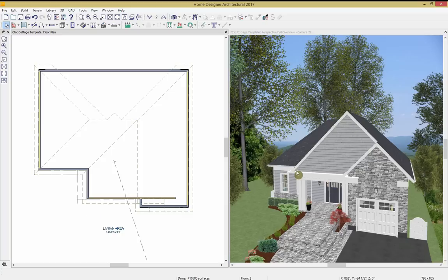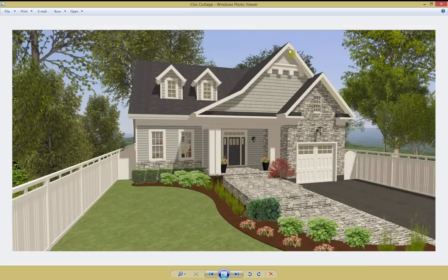What I mean by that is that it didn't create a gable that came up and back down, it came up and met up with our original gable here. So it nested them. So now, if we take a look at our plan again, or our plan that we're creating, you can see we don't actually come down flat to meet up with this wall. We have two roof pitches coming off of this far porch wall.